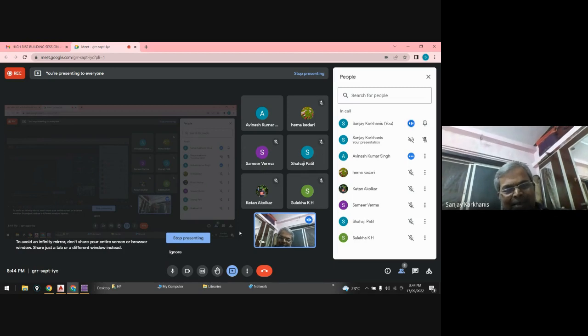See, for this you need very skilled laborers, and you need a different type of machinery. There are cables that are used along with reinforcement, because only reinforcement and concrete are not capable of carrying the stresses due to the commercial loading coming on the slabs. So they are using post tension cables.